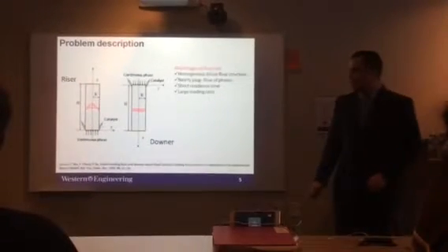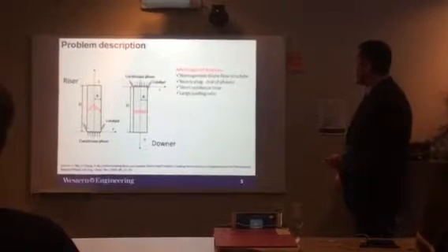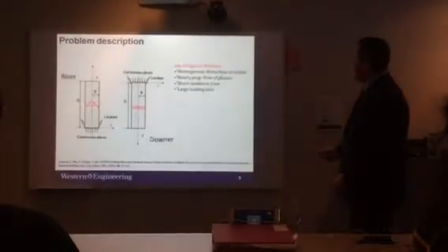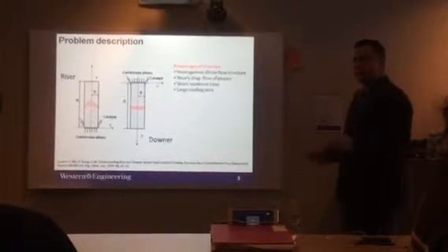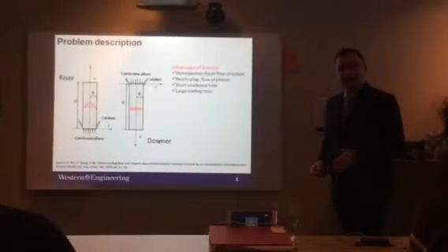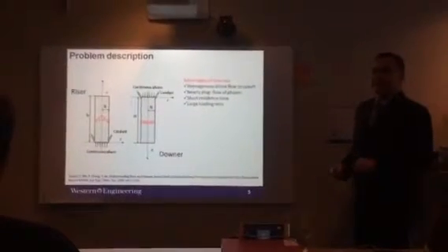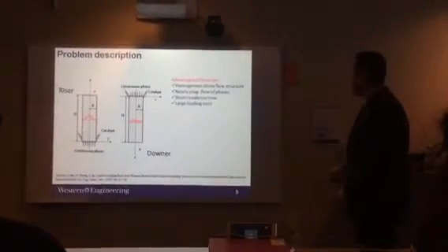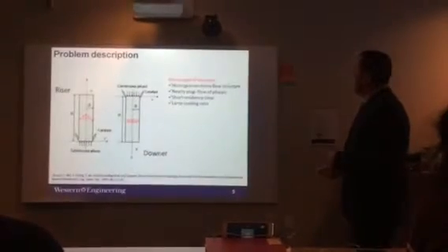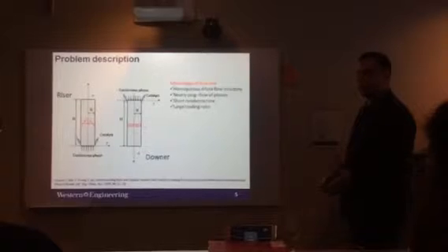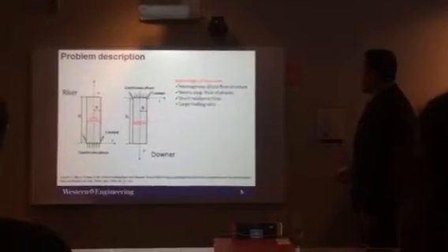In the downer, the main advantages are a homogeneous plug flow structure with better selectivity, a flat profile of phases, a narrow residence time distribution of particles inside the reactor, a short residence time because the back mixing effect is not there, and we can load the reactor with a large ratio between the catalyst and the fluid. So,